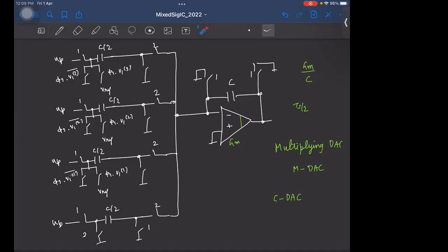So, I mean, look at it here, right? The first 3 branches take the input as well as the DAC, right? And the DAC has how many inputs now? How many bits are there for the input of the DAC? I mean, ADC output is essentially the DAC input, isn't it? So for a 2-bit case, remember the ADC output is in thermometer code format. Correct. These are directly feeding here. Okay. So here we have 3 branches, and these 3 take the DAC input, and 1 additional branch for the input alone.